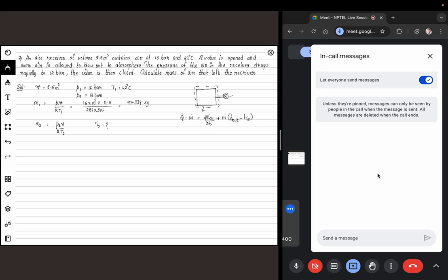We also have the mass equation where dmcv/dt is the mass increase minus mass out. So m dot in is 0, since there is nothing coming inside, so I've just removed the other term here. There is no inside term, there is only the outgoing one.